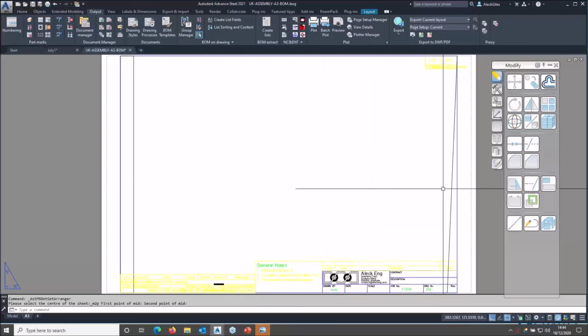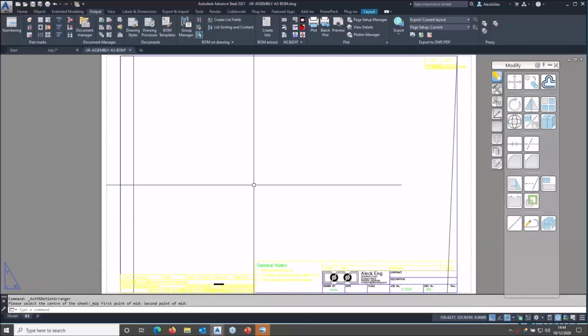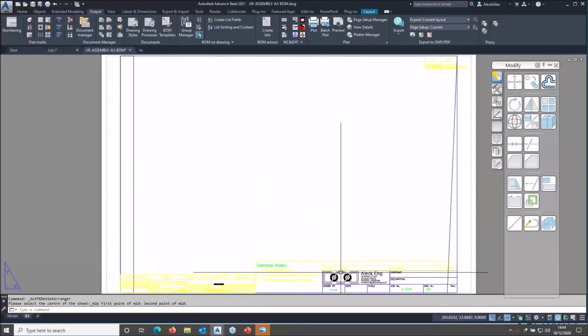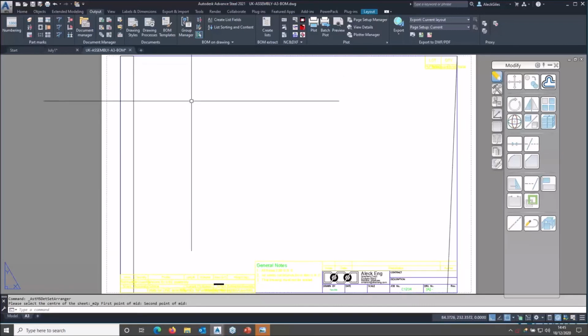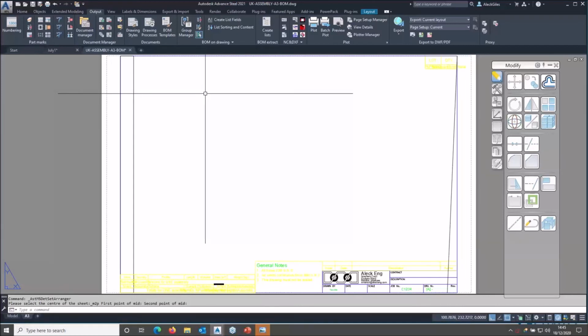But if I had quite a big chunky title block, or quite a small title block, but you had a lot of notes in the top left corner or something in your border, then you don't want it to go over those either. You want it to ignore that area and keep that area clean. So if I wanted to keep that area clean, I could reserve that area. I could create a reserved area saying don't use this space, and it will find a way to fit around that space.